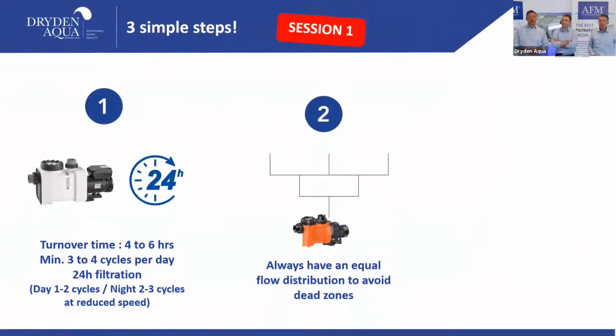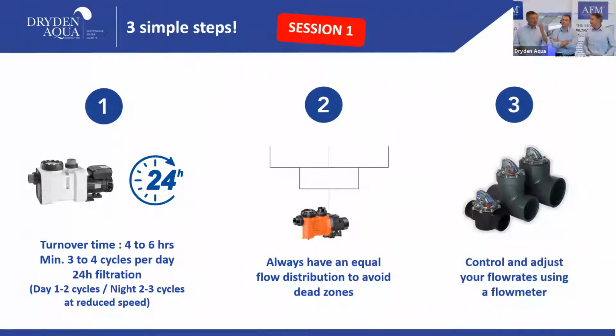Remember, this is the summary from session number 1, where we said ideally you have a turnover time from 4 to 6 hours. Small pools, heavy loaded pools, more something like 4 hours. If you have big pools like 100 cubic meters, 6 hours is acceptable.